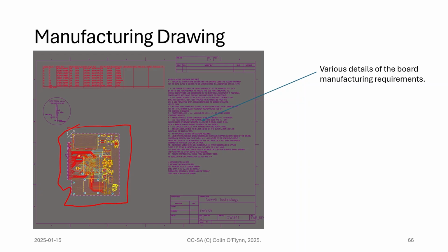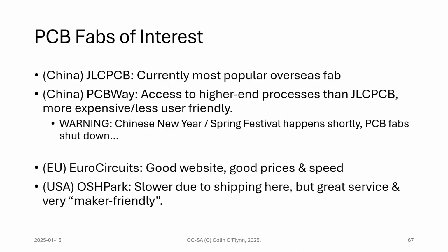It has drill markings. You may have a separate Gerber drill file that has this as well. In this case, I have some information about the drill sizes, and I have details about the finish I need. This has a card edge. Here's the card edge dimensions, things like that. So this is pretty common to have in a design as well.